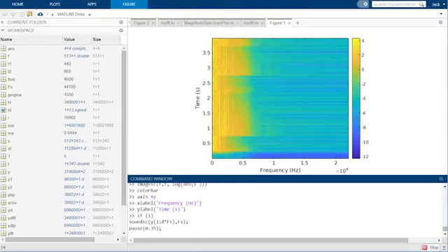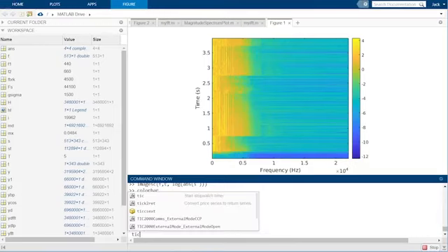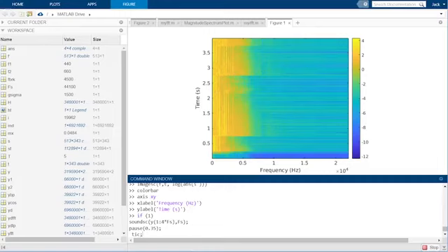At this point, we wish to begin showing our line. tic starts the clock at time 0. And we will keep drawing the figure in a while loop for 4 seconds. So we use a while loop that stops when our time tm becomes larger than 4.